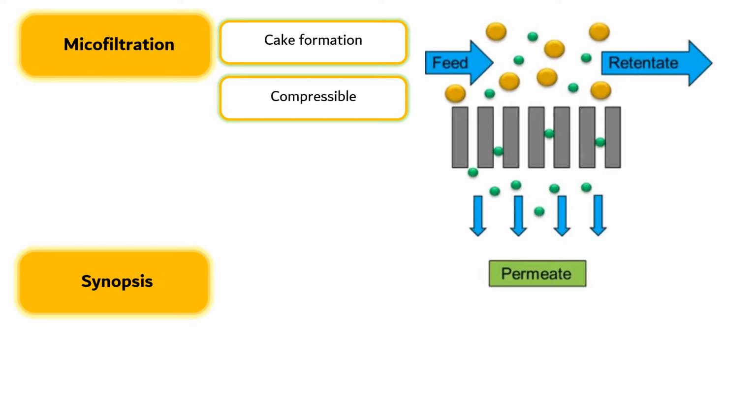The figure on the right shows that filtration without the formation of cake can be achieved using a large cross flow tangential to the surface of the filter. At the same time, the flow normal to the filter is relatively small. The large ratio of cross flow to the flow through the filter minimizes the accumulation of cake.